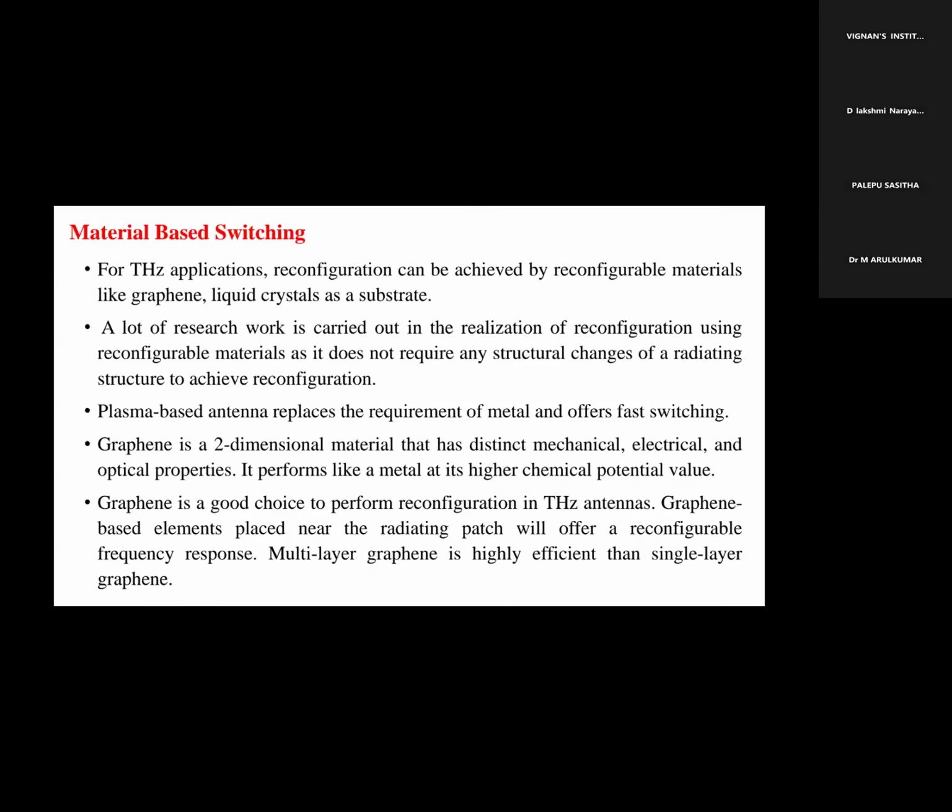So, material based switches. For terahertz applications, reconfiguration can be achieved by reconfigurable materials like graphene and liquid crystal as a substrate. A lot of research is carried out on the realization of reconfiguration using reconfigurable materials as it does not require any structural changes of the radiating structure to achieve the reconfiguration. Plasma-based antennas replace the requirement of metal and also offer fast switching.